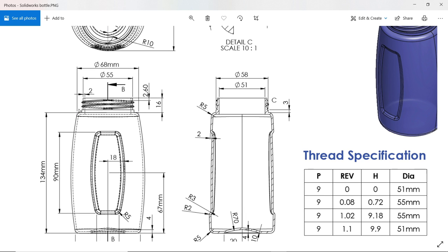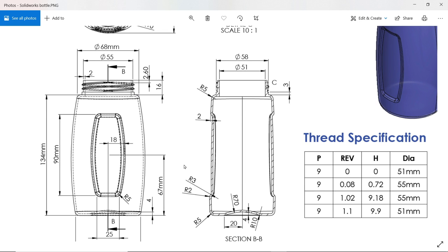Then on the upper edges we will extrude 16 millimeter, and the diameter is 55, up to 16 millimeter. Okay. Then we need to also make a hole. Then we will use the mirror tool to complete the full body. And let's see some more. And these corners R5 here also.